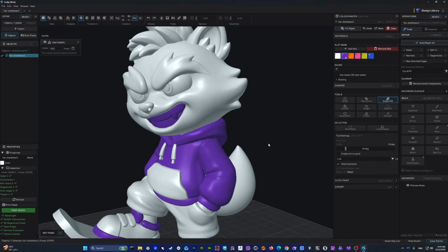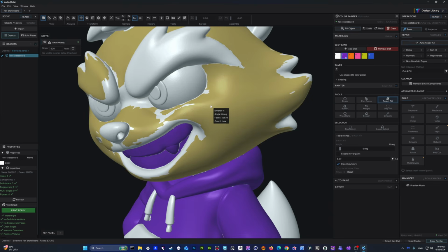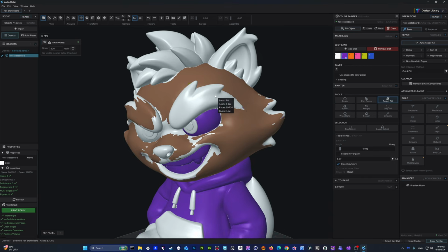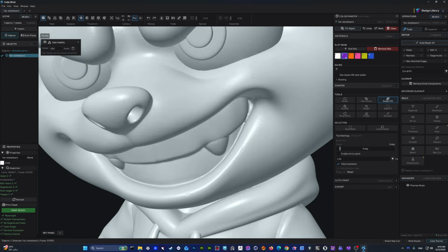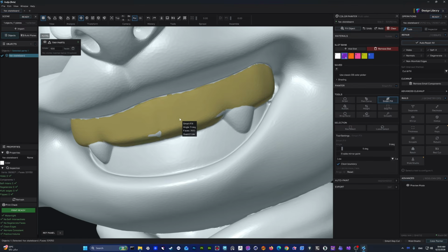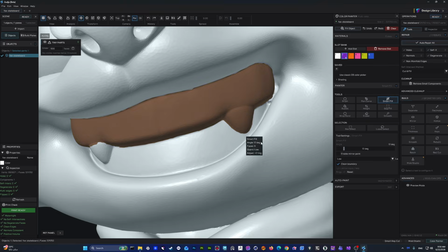So you have full control with shift and right click, and just press on the part you feel the preview is perfect for it. And also, if we go to teeth right here, the detection doesn't affect good, because sometimes the mesh or the polygons of the mesh are not perfect. So we can control the shrink from here, if you see in keyboard. It's gonna be less, or you can increase around it if there are tiny parts you want to detect, as you can see.